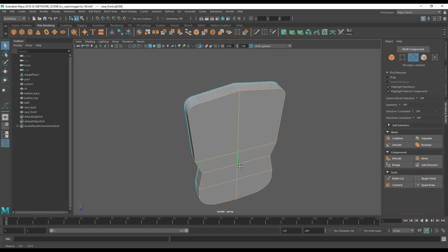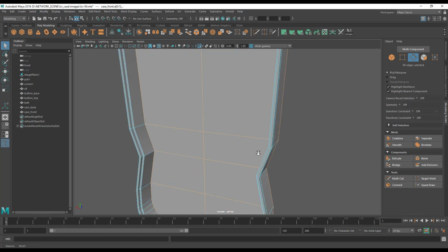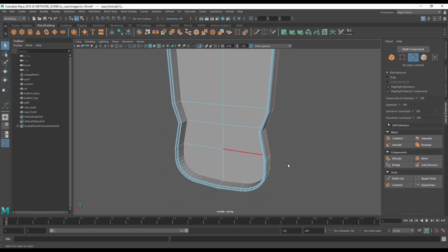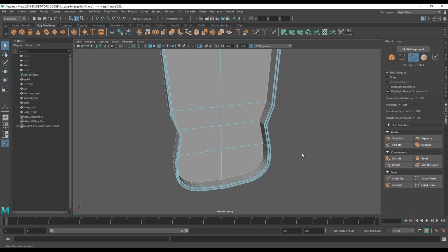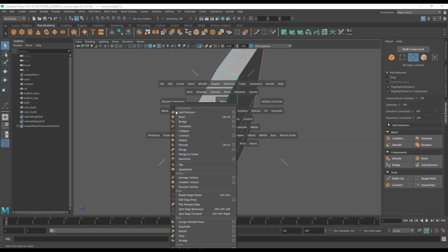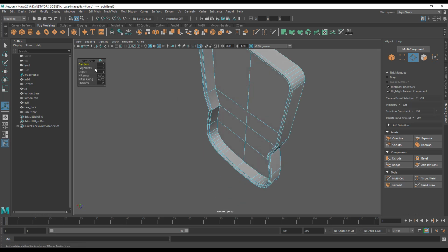honestly you can do this with just selecting the faces, but every once in a while Maya will give you some issues with that, and as we have a very limited number of internal edges here to deselect, I'm just going to take no chances. Now we very much will have to delete these faces in the end anyway, but right now we need them for our bevel operation. So edit mesh, bevel, and we can decide on the sort of fraction of bevel that we want. So let's see, what do we want?